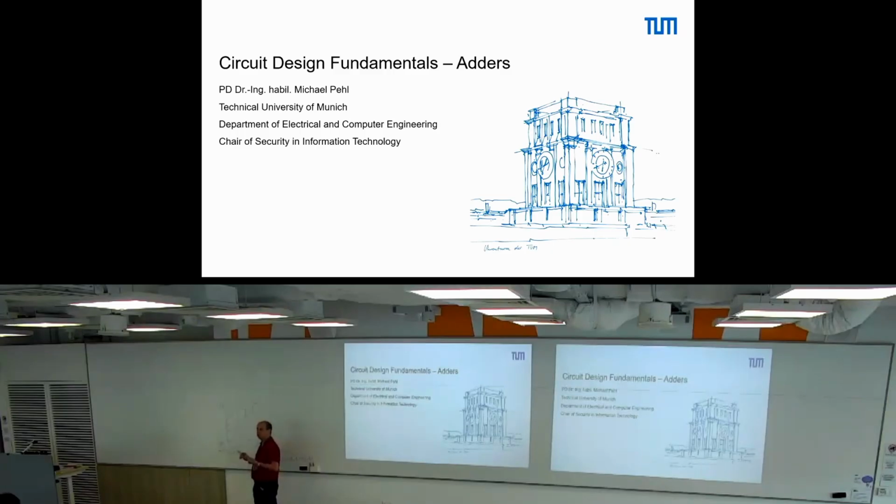The third was it is not commutative. So it is forbidden to move G2, P2 to the right. So this here is not an adder. So we actually proved this is not an adder. What can I do to fix this? What can I do to make this correct as an adder, at least for this carry here? Add another tree.